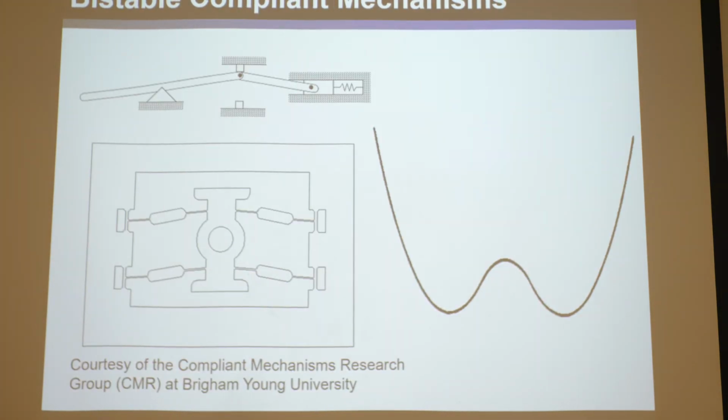Okay, so another neat application of compliant mechanisms is that they can be used to achieve multi-stability. Look at this switch up here. This is a rigid mechanism, but they put a spring in there. You can imagine it's stable in this state, and then you tick this switch up, and it rotates around there. On the way to lifting it up, this spring becomes very unhappy, with a bunch of energy stored in it. But once it gets over the hump, it'll snap to the other one, and the spring will relax. So you can see it's a switch. There are two states of happiness where it stays put, and it takes a force to make it unhappy to get it to the other state.